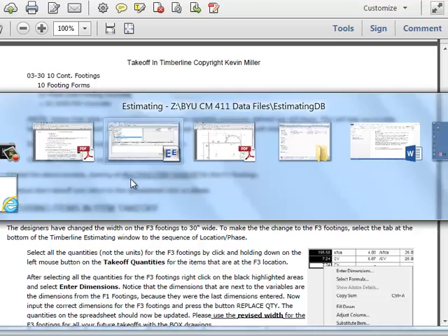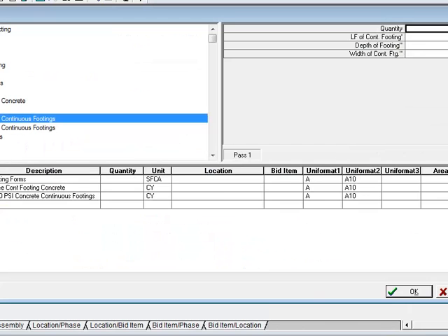And then make sure the width, we'll say, is 18 inches. Mine didn't pop up with a width. Do you have 3 items down here? Should be just 10, 20, and C30. It didn't. So you double click on each one to add it.